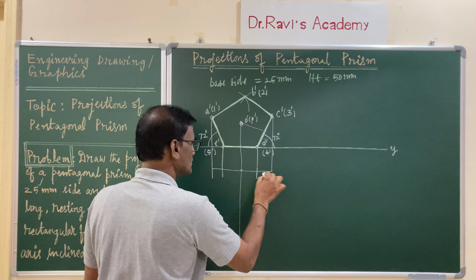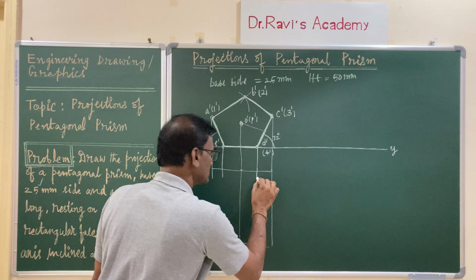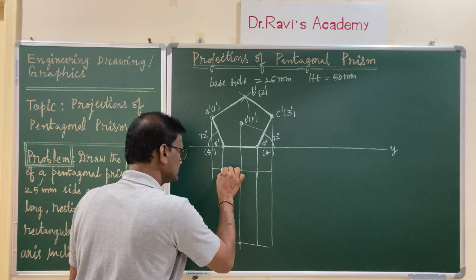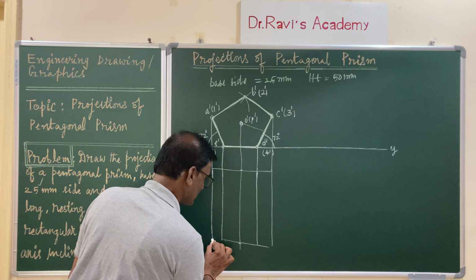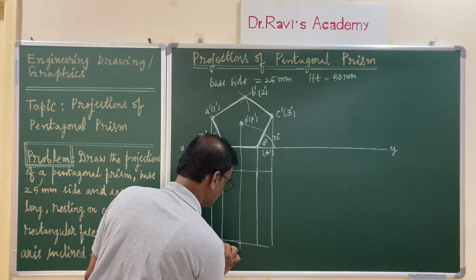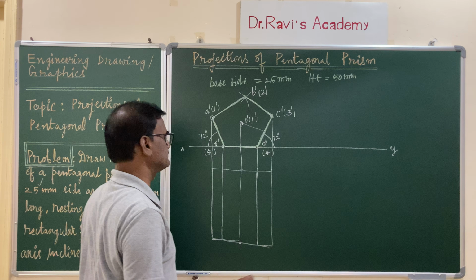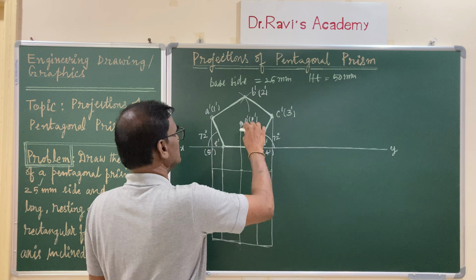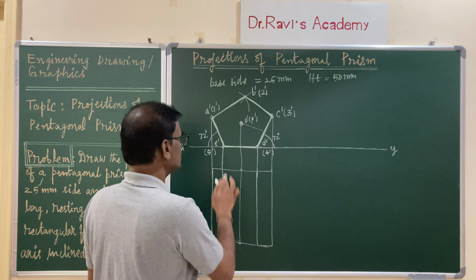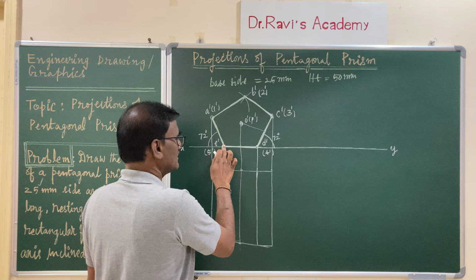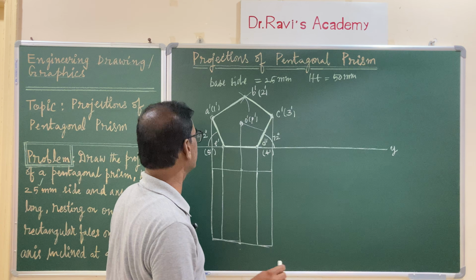Let us do this with a 2H pencil. And here also draw the perpendicular, drawing the parallels as well as perpendiculars. And complete this. The height is given, it is 50 mm. And you see that this longer edge is passing over this. Now observe carefully here, this longer edge and this longer edge both are hidden edges.